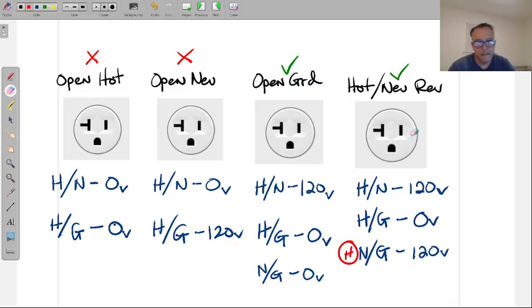Now, ideally, we don't like to do this hot. A switch, I have some tricks to do it hot. But I don't like to land on terminal points of devices, switches or outlets, hot. Like bring the wire hot to the terminal point. I don't like to do that because the yoke is metal. I'm holding on to it, otherwise the outlet's not going to float in the air for me. I got to hold it. So if I mess up with this hot wire and I touch the metal, now I can get shocked.